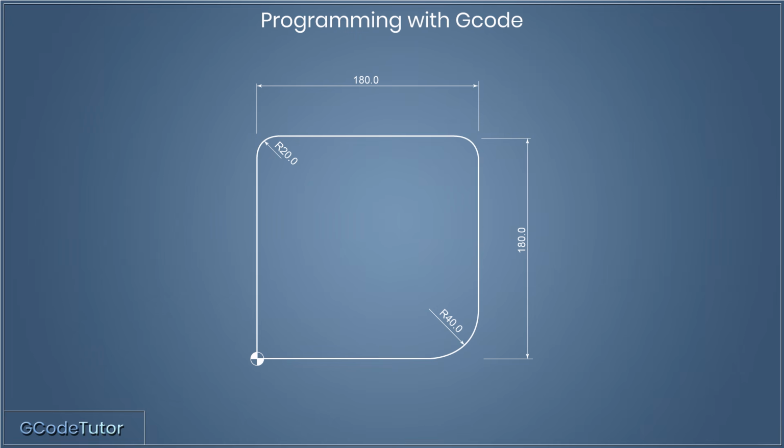A good way of getting to know the style your machine likes is by outputting a file in Fusion 360 using the post processor, and then it prints out the program that the machine likes to read. Like for example, the safety line would be set up the same, and certain M codes and G codes that like to be active at the beginning of the program will be there. So you can get a general idea of how your machine likes the program to be written by outputting files from Fusion. But saying that, it's best not to get too bogged down with this concept. I tend to teach generic G codes quite often, so you can put it into any project or any machine and it gives you an idea of how it works. But just be aware that each machine likes it written in a certain way.